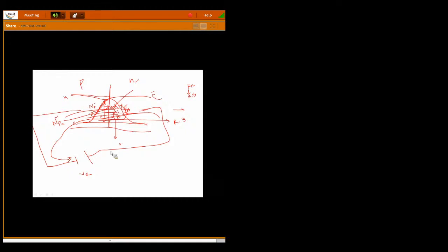That's why in the reverse bias, initially, whenever you change immediately from forward to reverse bias, a larger amount of reverse saturation current will flow. After some amount of time, it settles. In the sense, all the minority carriers near the junction, a large number of charge carriers, will diffuse according to the DC source you are applying, and they will settle at some point of time. That time we call the storage time.